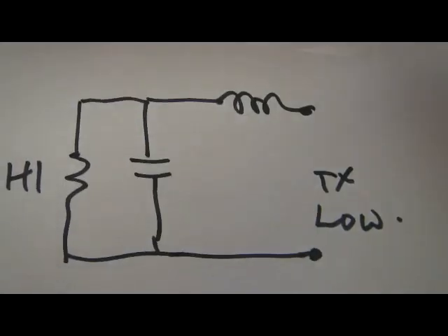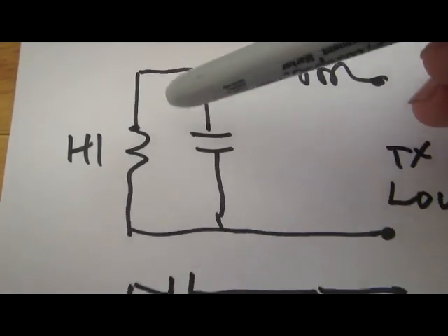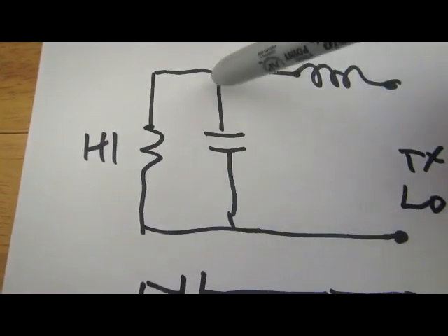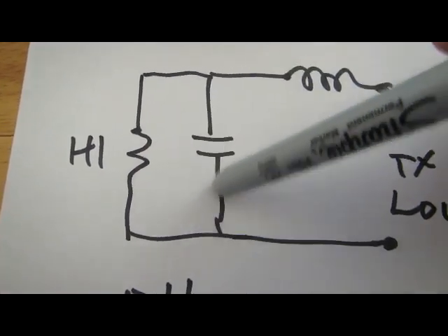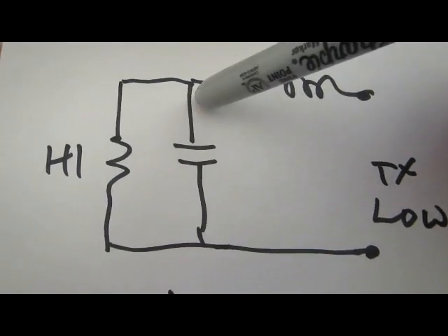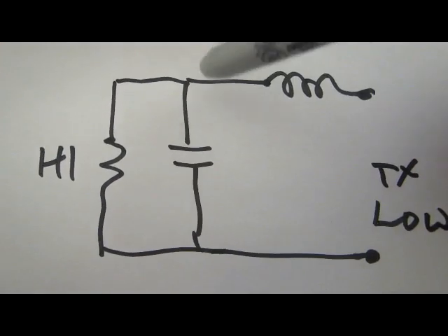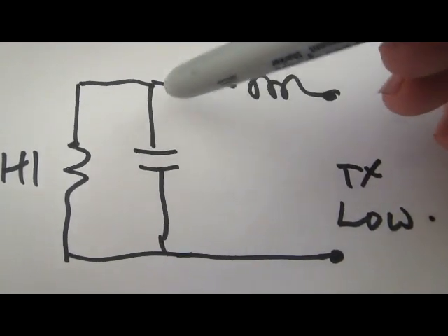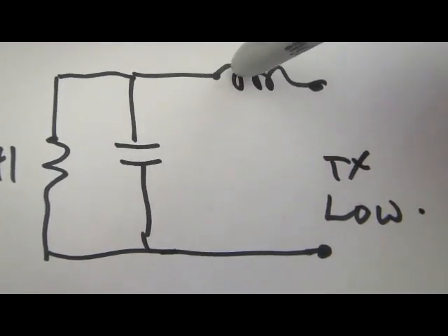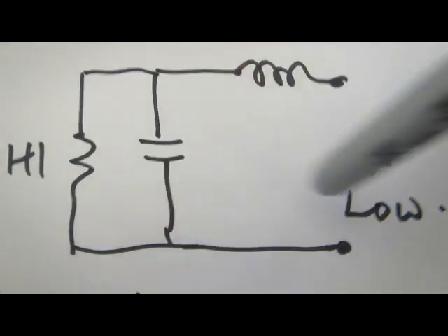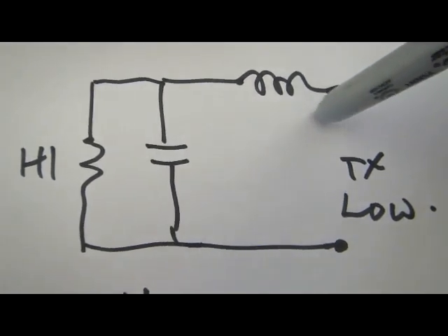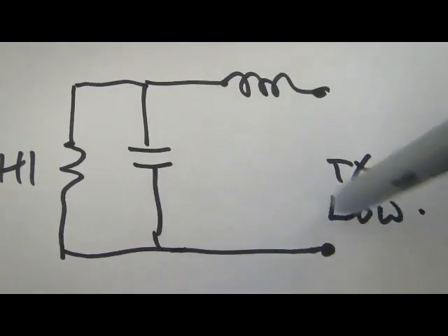It can be either way round. In this case, this is where we have a high resistance. So we've shunted across. We should put a reactance here in parallel with it to generate the series value that we want, which is then tuned up with the L. So for high to low, this is like the beginning of a parallel circuit, and this is like a series circuit.